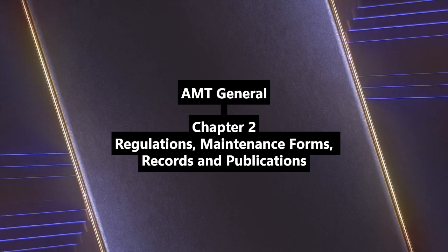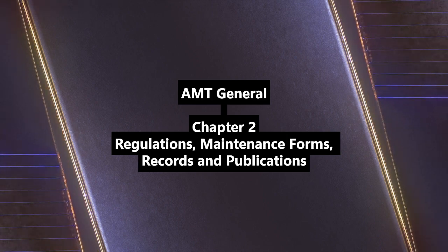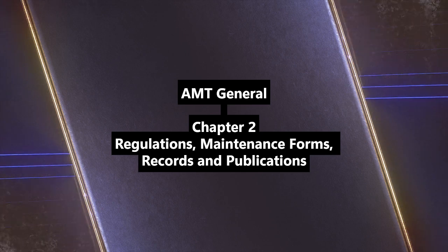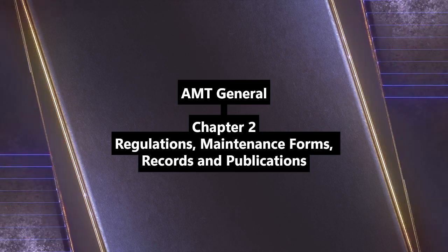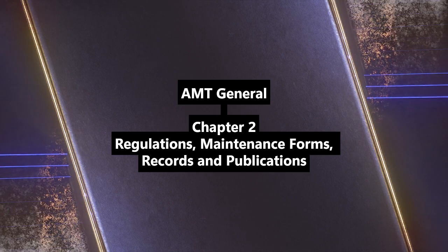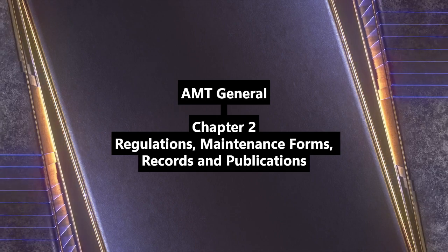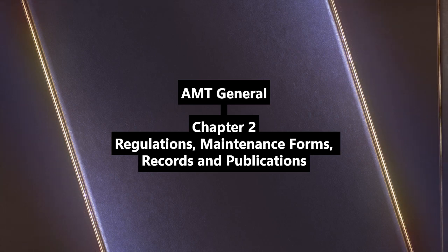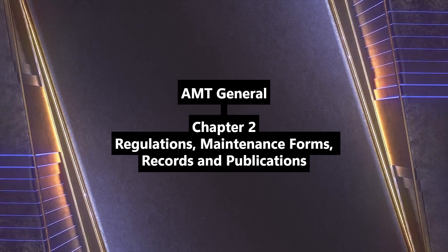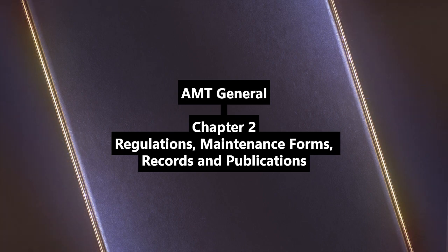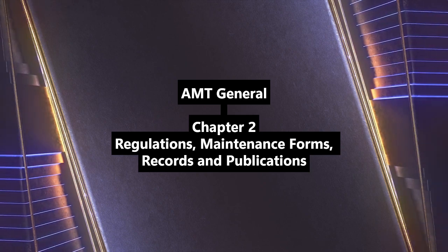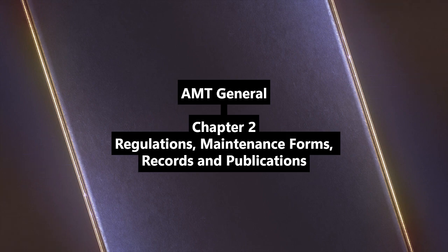Okay. Airworthiness directives, ADs. We covered these, but maybe a quick recap. Legally mandatory rules under Part 39, issued for unsafe conditions likely existing in other products of the same design, require corrective action. Issued how? NPRM, then final rule. Emergency ADs. All of those. Emergency ADs require immediate action upon notice. ADs describe the issue, affected products, required action, compliance time. Numbering is year by weekly period, sequential. Compliance is mandatory per 91.403. You can request FAA approval for an alternative method of compliance, AMOC.